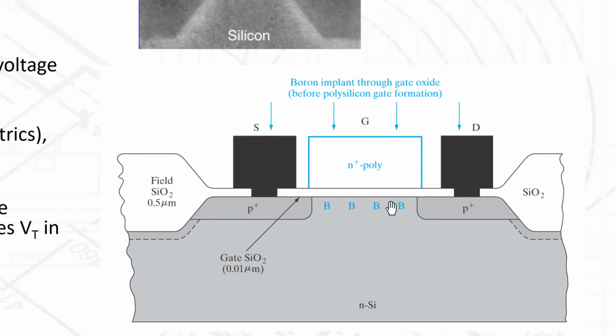You will decrease the threshold because you make this area closer to the B plus. Yeah, you got it. That's right on. Exactly what we're looking for. You see, in a P-channel device, in order to turn the transistor on, we have to invert the material under the gate to P-type, right? So by implanting some boron atoms in there already, we're already changing it partially to P-type.